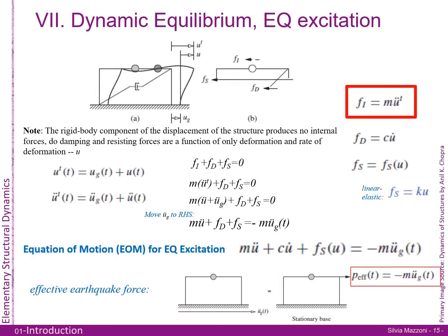A very important consideration that I want to highlight early on is what happens when we have earthquake excitation. If you go to the previous figure, which I can't do right now, we actually had a force acting on here. Well, when you have an earthquake, you don't. It's not like you have a higher being there pulling you to the side. What is actually happening is the support is being excited.